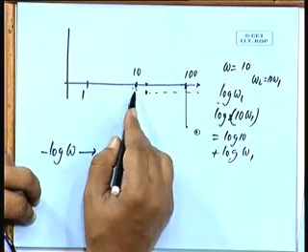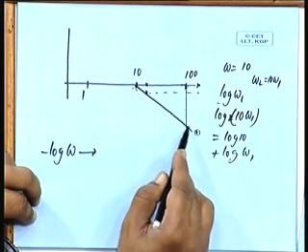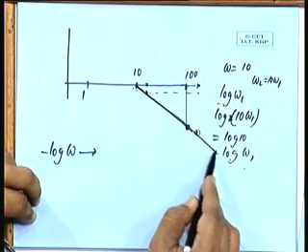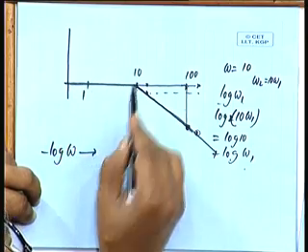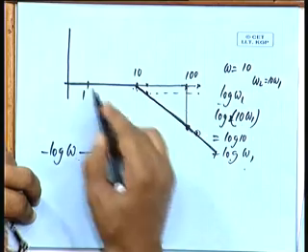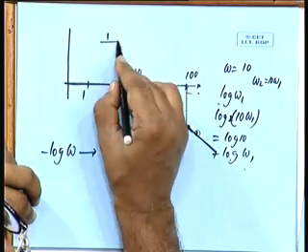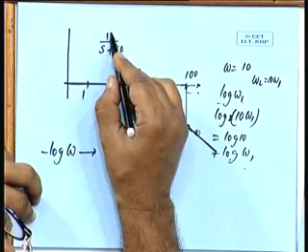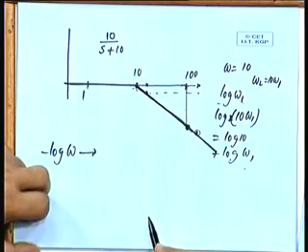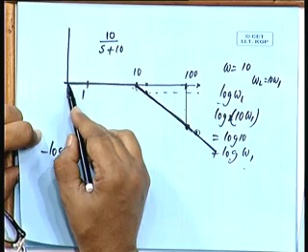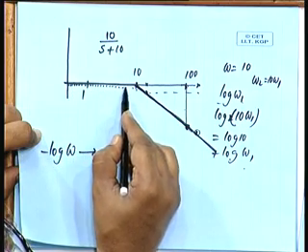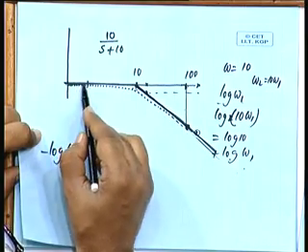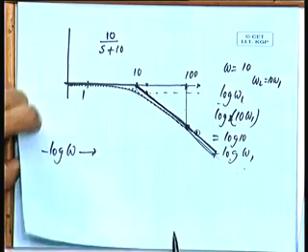Here it will be in the negative region. So, I can join these points, 20 dB at 100, 40 dB at 1000 and so on, by a line. So, it will be approaching either this one or this one as the frequency increases. So, these are the two asymptotes corresponding to a function 1 by s plus 10. Okay, it is 10 by s plus 10. So, the actual frequency response may be going close to this, it will be meeting this asymptotically, this one also asymptotically. So, the actual curve will be somewhat like this.